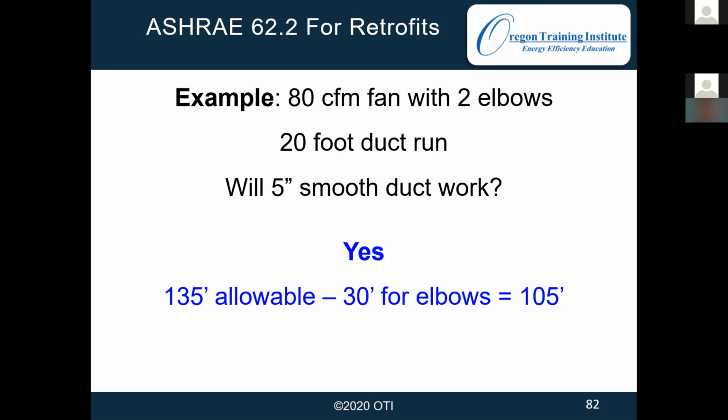The lower our airflow is, the more our ASHRAE fan is going to have to make up for these fans that don't move enough air. And if our ASHRAE fan isn't moving enough air, now we're not in compliance. So we would fail inspection and we would need more airflow to meet ASHRAE. So we definitely want to get it vented well so we don't run into those sorts of issues where the fans aren't moving enough air.